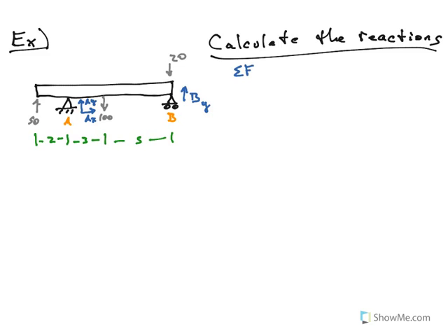Well, I've got the sum of the forces in the x direction better be equal to 0. The sum of the forces in the y direction better be equal to 0. And the sum of the moments is equal to 0. What these equations tell me, the first one, is this plank, this system is not moving left or right. It's in equilibrium. It's not moving. And if it's not moving, there better not be any net force in the x direction. Because if there is a net force in the x direction, then it's accelerating in the x direction, which means it's moving. And of course, the same goes for the other two. The sum of the forces in the y direction being equal to 0 just tells me this object's not moving up or down. And the sum of the moments equal to 0 means this object is not rotating. And that's what we're going to assume. That's why this part of engineering is called statics. The system is not moving, it's static, it's in equilibrium. So all the forces and all the moments must add up to 0.